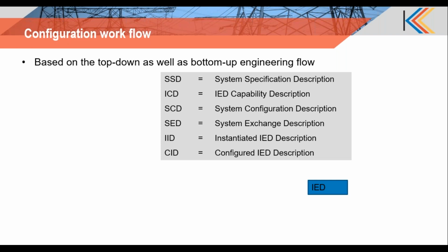Now, the thing is, all these configuration files, all these variants of the SCL files, have the same common intention. That is exchanging the configuration information between your applications and the IED that you are configuring. So all these files basically have the same end objective: getting the configuration correctly downloaded into your IED so that your IED is working as per the design.